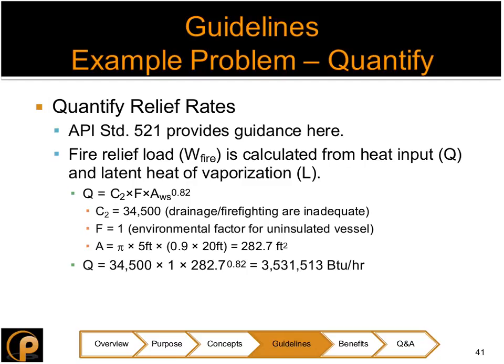Okay, thank you. Recently, a legal case permitted more than 3% drop on PSV inlet. Is this ever wise? I don't know that the word permitted is accurate. This is also a pretty tricky point. The idea, and what everybody feels safe about, nobody's going to argue that this is something bad to fall on, is to limit your inlet pressure drop to 3%. The reason for this is because of some reductive logic that has been formulated over the past several decades to minimize or eliminate chatter in a PSV.